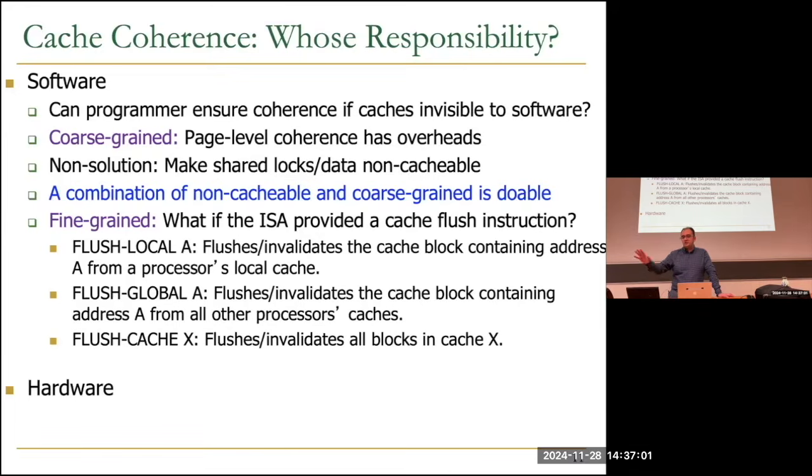So they said, okay, we're not going to support cache coherence at all. And everything should be handled by the programmer. And that's why, in the end, even well-experienced programmers cannot really use CellBE easily. I'm not sure about other editions of CellBE. I haven't followed up. I only worked with that CellBE, which is used in PlayStation 3. But it was really a headache to program and use. So even IBM engineers, I guess, after that also realized that that wasn't a really good idea. So there should be something in between, not completely software.